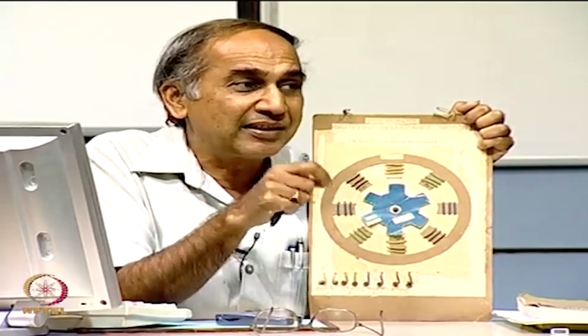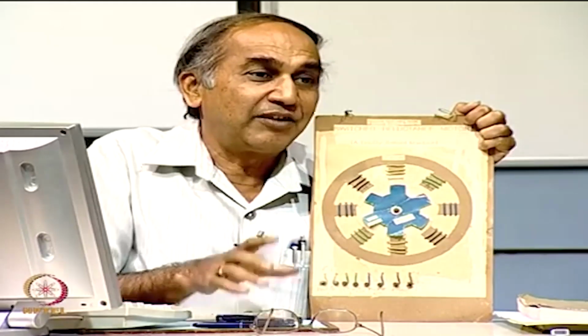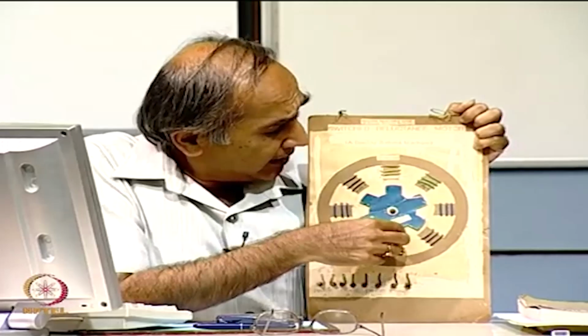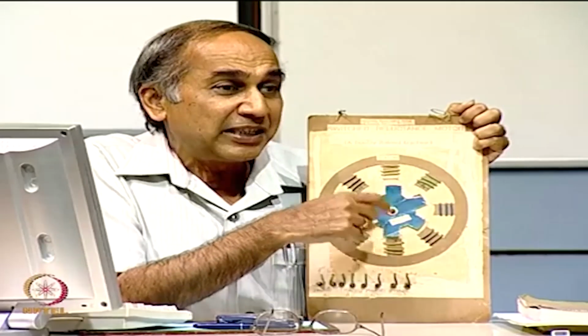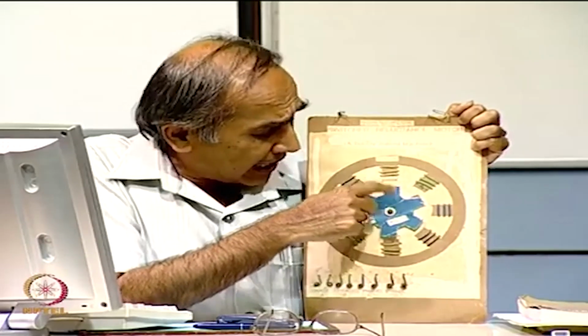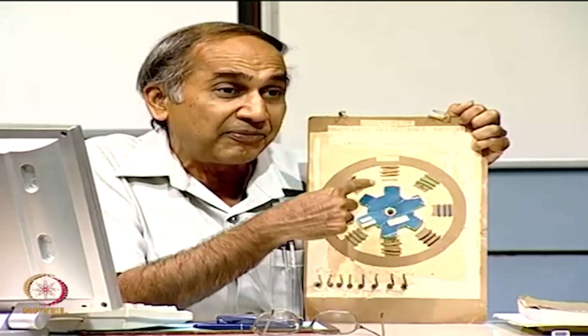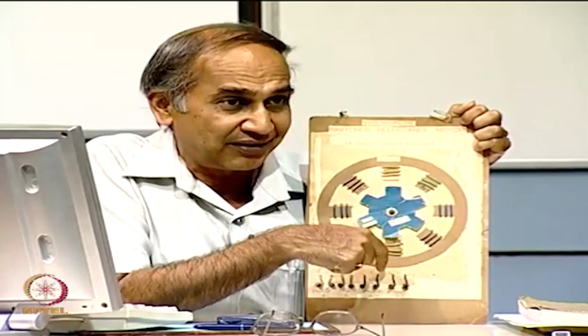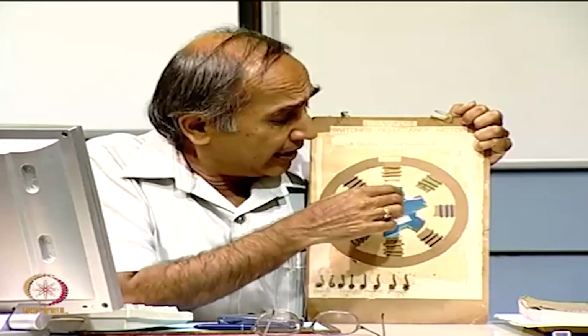What is inductance? It is the flux per unit current, and flux per unit current is not the same because if you increase the current, flux will be less due to saturation. If it is aligned, it will be subjected to saturation because in the aligned position there is more iron in the flux path. If unaligned, there is more air.